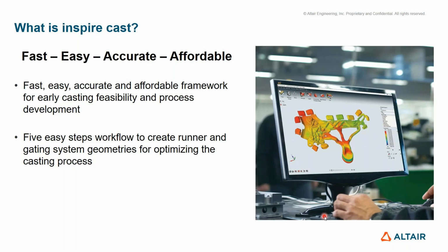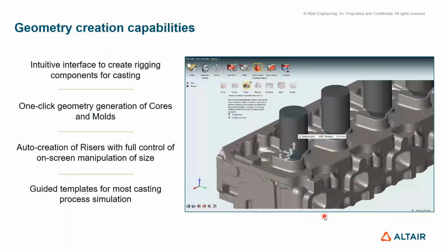So it has intuitive rigging components for casting simulation. In a single click, you will be able to generate core and molds, and it has auto creation of riser with full control of on-screen manipulation of size of the riser. And it has guided template for most of the casting simulation process like sand casting, high pressure die casting, low pressure die casting, and so on.